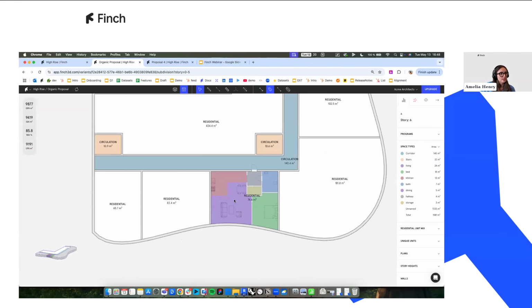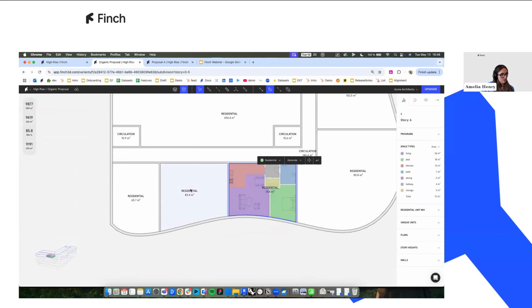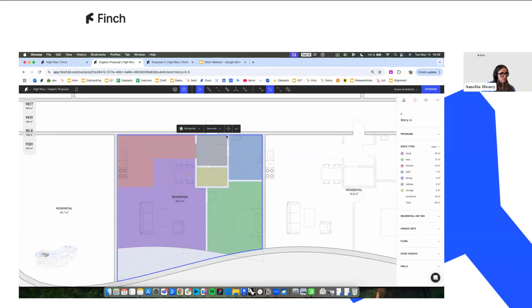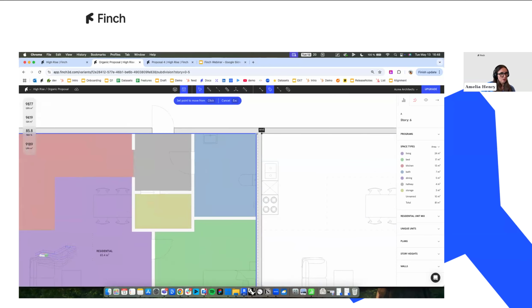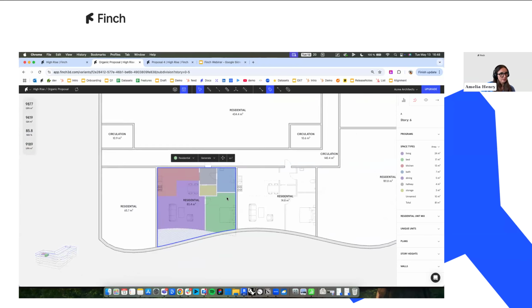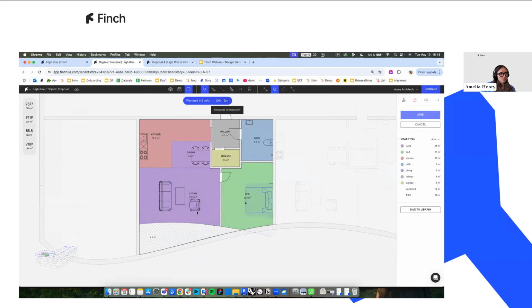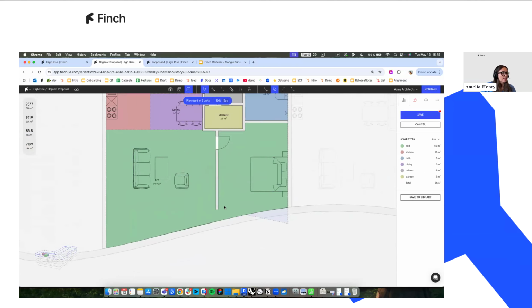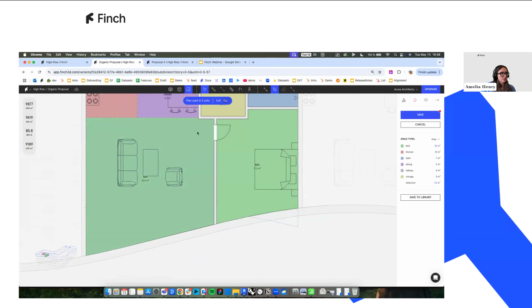And now let's say that I want to use it here. So it's similar. We want the same base, but of course we want it to fit into this unique shape here. So first thing I do is just Control C, Control V, so your typical copy paste, and I'll just align that right there. And then if we jump into the unit, we see that it's actually maintained that structure there. So first thing that I will do is just fit bounds, which is basically exploding that plan to fit this unit. And then it's just a matter of some real minor changes here.